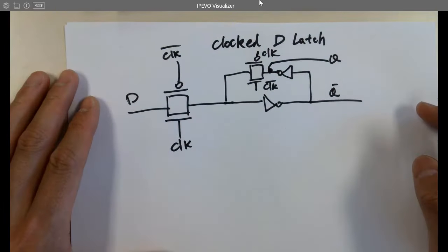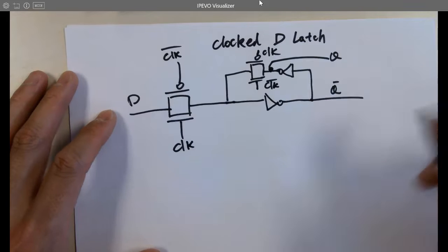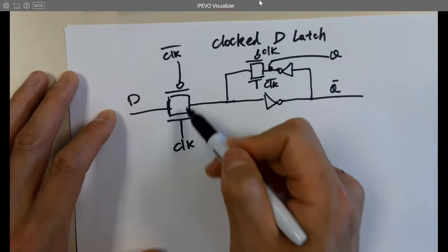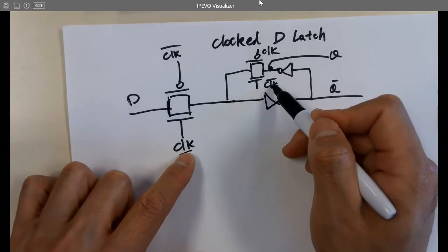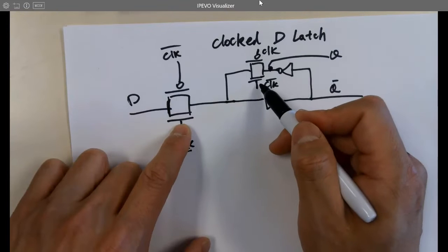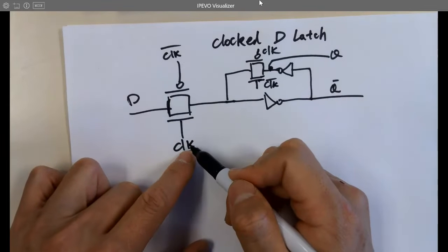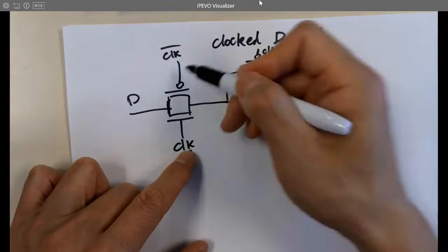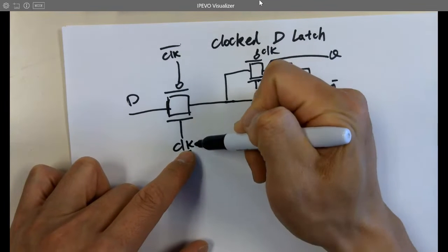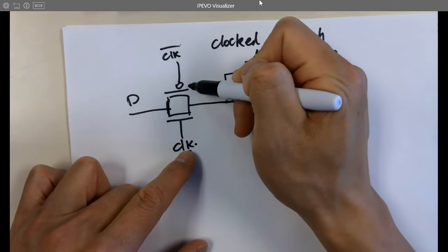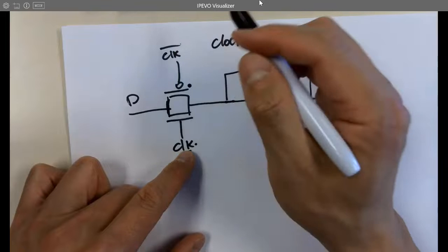What's happening here? Yeah, that's the transmission gate, NMOS and PMOS, right? So this is clock bar. These are inverted signals going to the two transmission gates. So if this is on, and the PMOS has the clock bar signal, an inverted signal of the clock, what about this PMOS? Yeah, on as well. It's a trap. I'm waiting for you guys. It's off.